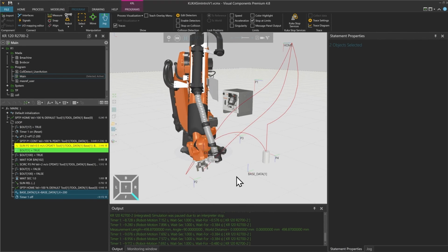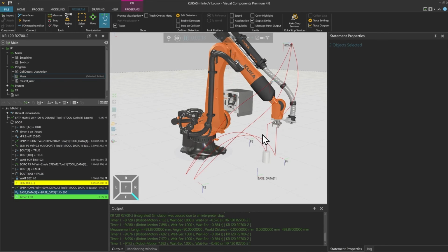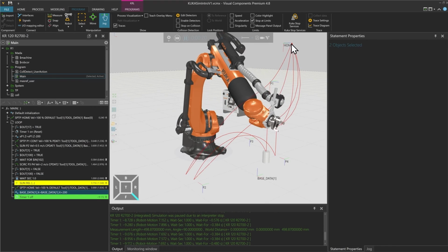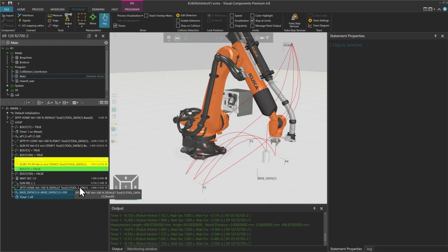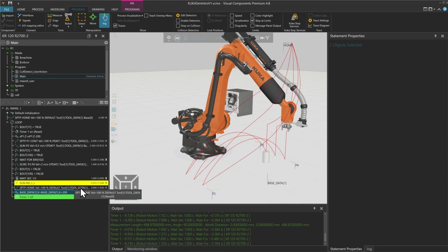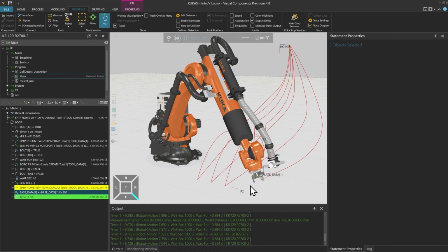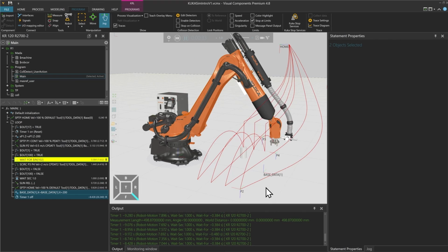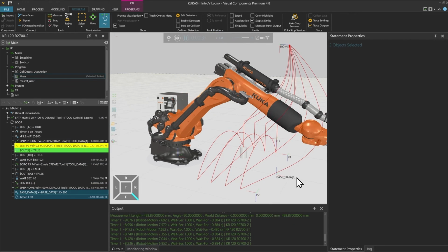And now my base shifted, so I have 200 millimeters up front and it will do a new shape. But it will go to my original home position because this is in relation to base 0. And you can see that it iterates over and over again until I run out of the reach of my robot. You can have a look at this when this happens.